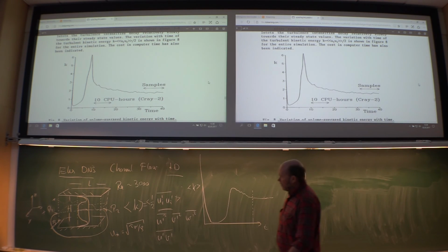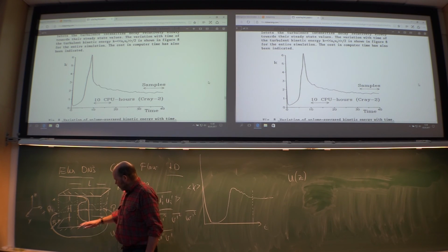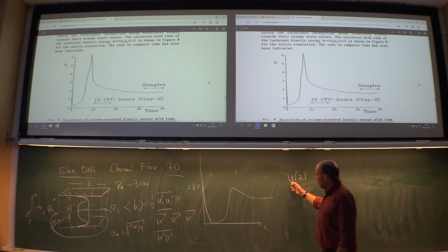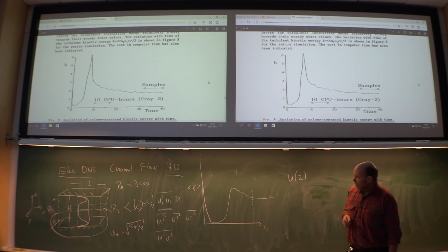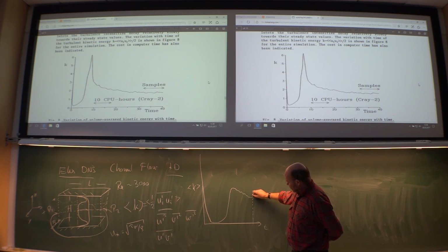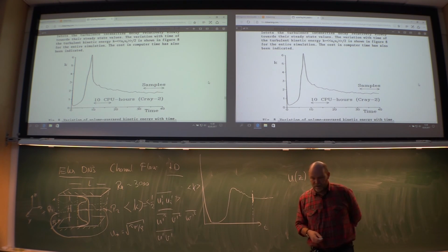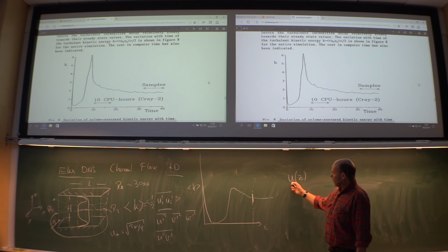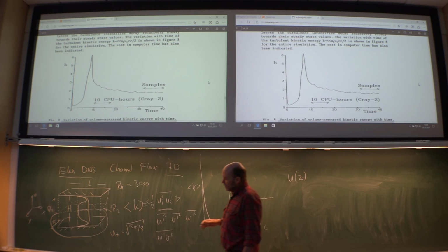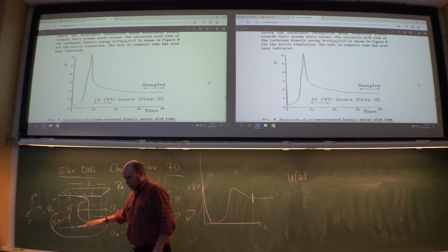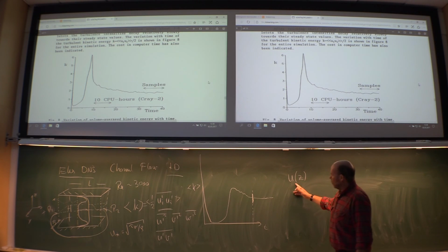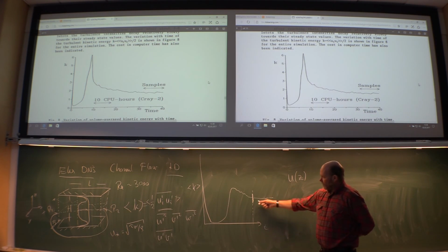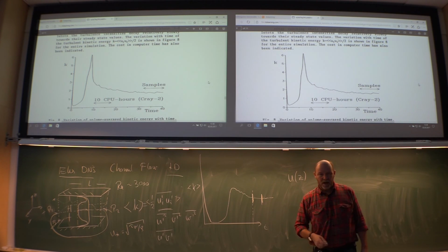You could do the averaging for each plane for one single time level. Yes, that was okay, but it still wasn't good enough to have a nice and smooth solution. So you simulate in time and take a snapshot of the solution. There you have one solution of the Navier-Stokes, and you can create the averaging in x and y directions. But then the velocity profile wasn't so smooth. Then you simulate further, and do another sample.